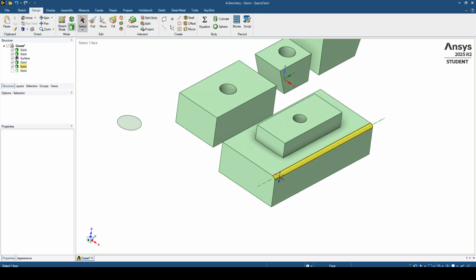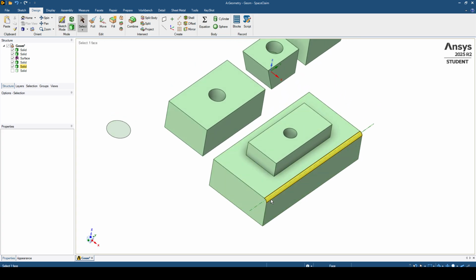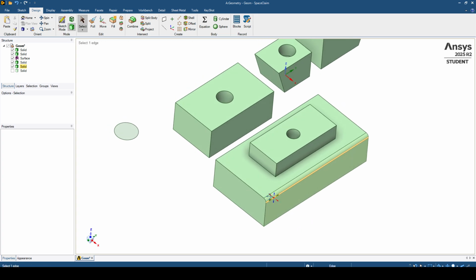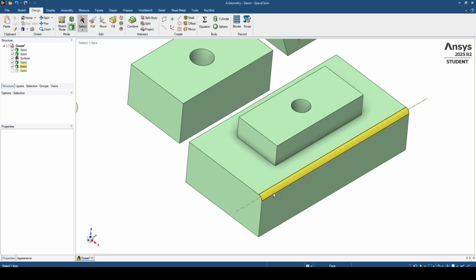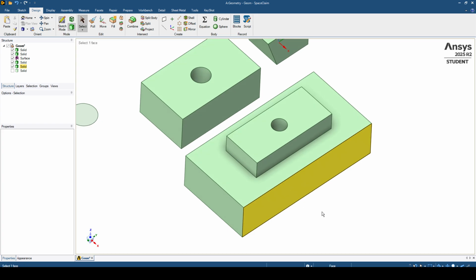this side. But I wanted to do this on all four sides. How to do that in a proper way? I will delete this fillet for now and let's do it again. We can choose all four sides from the beginning by clicking on all these edges. I will click on this edge. I will click together with the Control key and choose the other three edges together, and as you can see we are now marking all four edges.